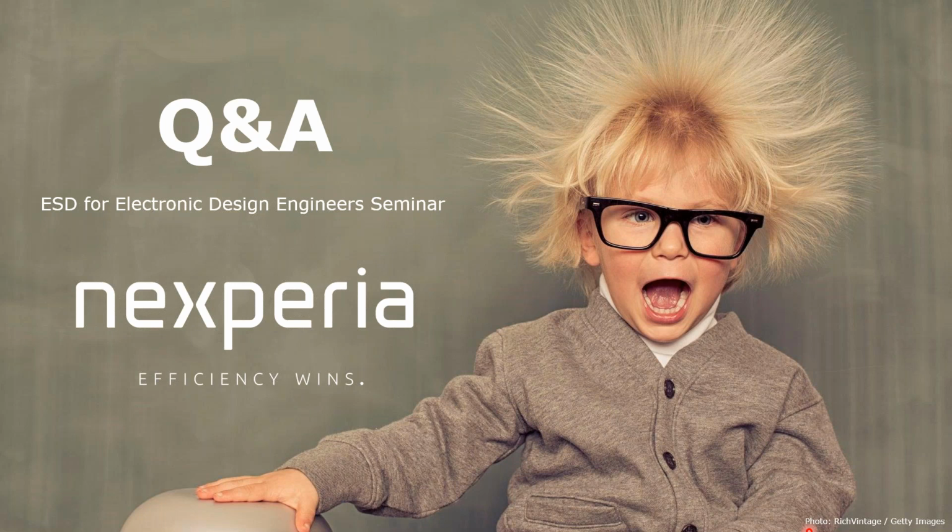Okay, so there's the question what a SEED model is. SEED model stands for System Efficient ESD Design. It's a topic we could easily talk for hours. It is a simulation method which is working with equivalent circuit models or behavioral description models, usually implemented in Verilog or VHDL. And this is actually simulating what is happening during an ESD event.